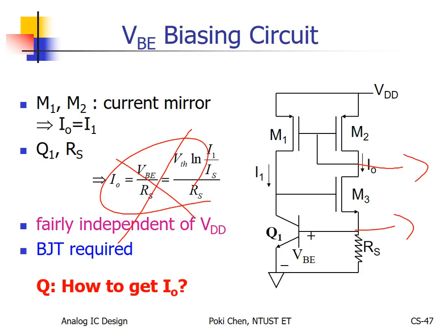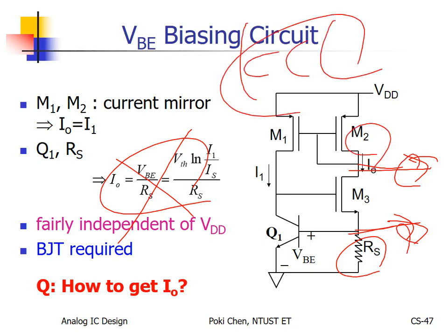And I promise you, it will become supply voltage dependent again. Because for the circuit you tap them out to, usually their operation depends on supply voltage. If this or that is supply voltage dependent, according to KCL, the final current will also be supply dependent.